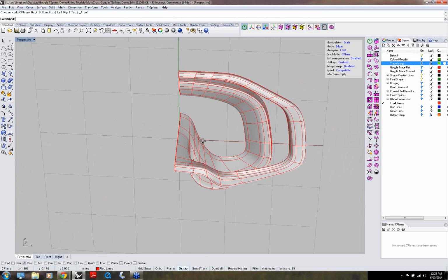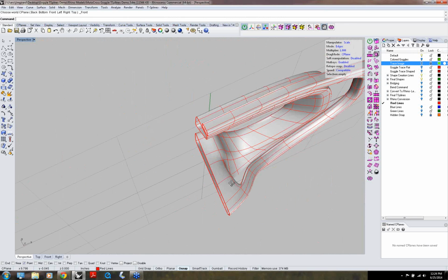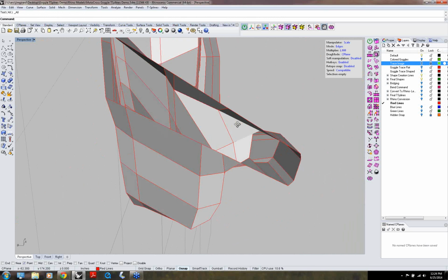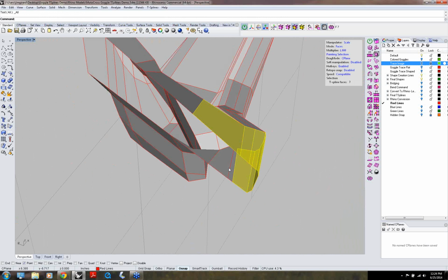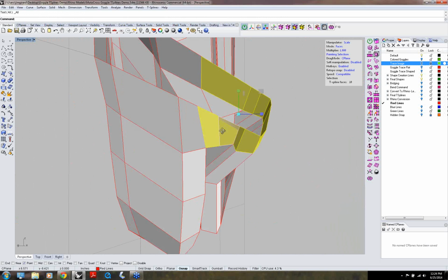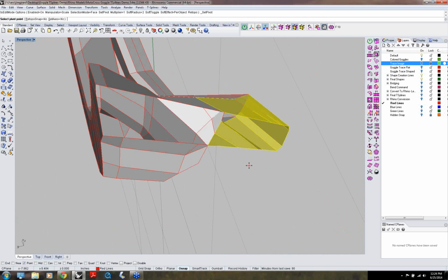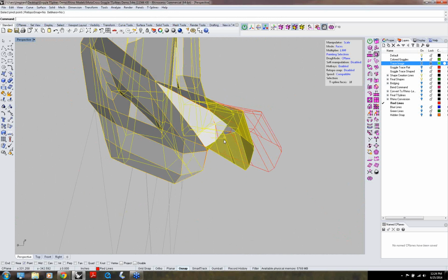So now we've bridged that one area for our exoskeleton look. And remember, when I move this out, I can go back to my box form, go to D, which is a hotkey for faces, and then they have another hotkey, P, which allows me to paint the faces, so I don't have to pick them individually. Then I go to T, which allows me to set my manipulator where I want it, and now I can pull that right back to where it was.